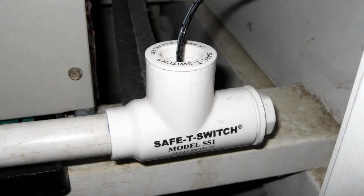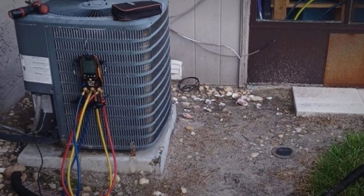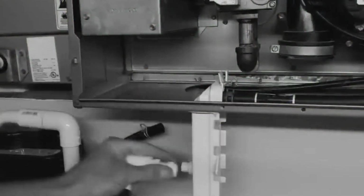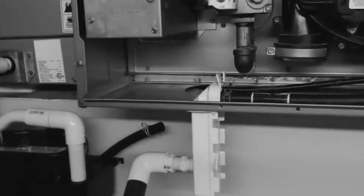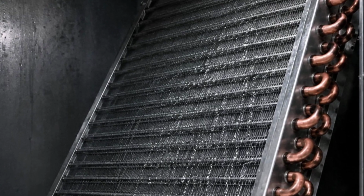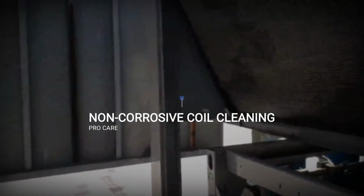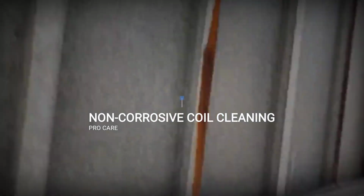Physical clog removal begins with backup, standing water, a float switch shutdown, or failed flow. Carrier and Trane point towards suction or mechanical clearing with professional service when the clog persists or the path is not safely accessible. Coil cleaning begins with the coil instructions. Carrier directs readers toward purpose-made, non-corrosive coil cleaning under professional care.